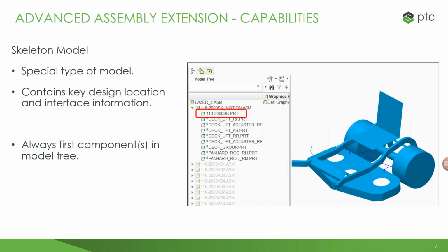An important thing to remember with this is all it's doing is holding all that key design information. So it's not going to show up in any of your bill of materials, in your mass properties, or if you're doing any type of simulations. No, it's not going to show up there. It's just basically a framework situation that's housing all that information. So that's important to note. And I'll go into that in more detail within the demonstration as well.